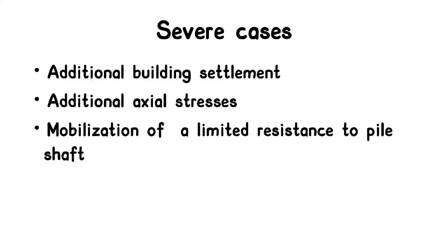Now, in severe cases, there can be additional building settlement due to this thermal cooling and heating, and there can be additional axial stresses acting on the pile, which can be tensile as well as compressive, and there can be a mobilization of a limited resistance to pile shaft.